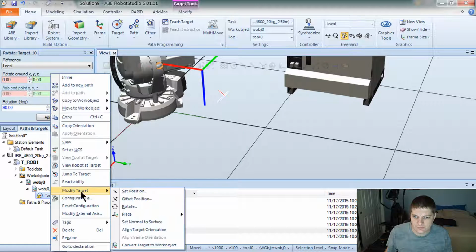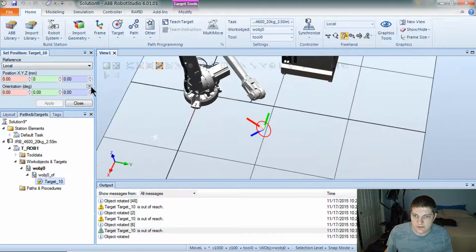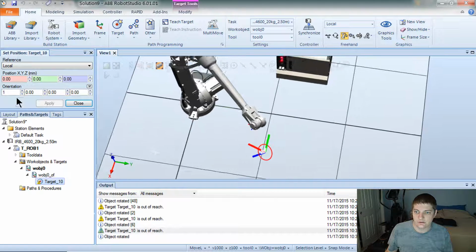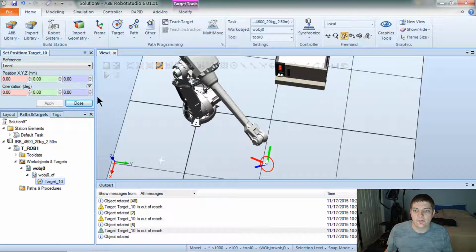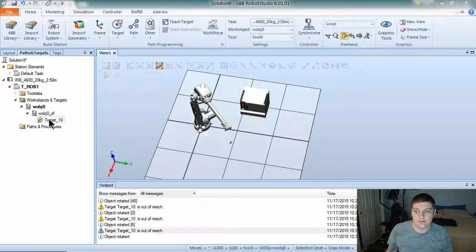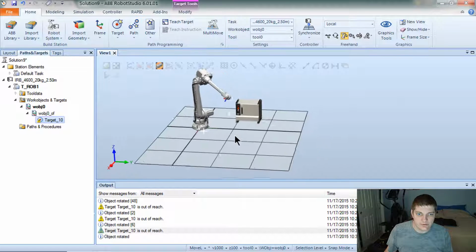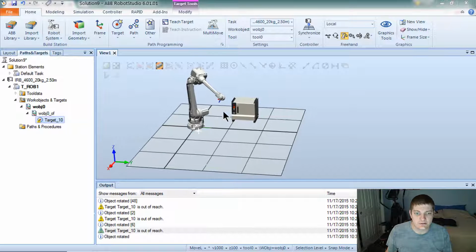And actually these systems technically, you can reference it in multiple ways. You can reference quaternions as well instead of Euler, but I'm more used to working in these. So the actual point will be stored in quaternions. So just something to know. You don't need to worry too much about them necessarily, but you can see the difference between those two values. So we have our first point, and I think that about explains the 6 axis, the 6 degrees of freedom,